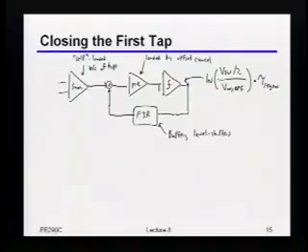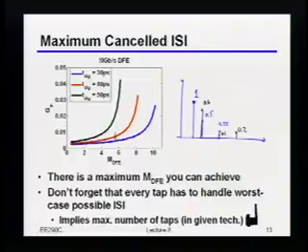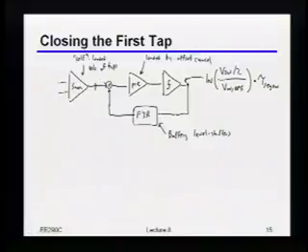Okay, and in particular, having to regenerate that small input signal can cost you quite a bit of time in terms of just regenerating, let's say, from 10 millivolts or 5 millivolts all the way up to something like a volt. Okay? So the issue you really run into here is that if you're running that DFE kind of close to the self-loading limit, but now you say, oh, no, oops, sorry, actually my comparator is a little bit slower, in this case, let's say, 10 picoseconds slower, all of a sudden, you might actually be completely infeasible, right? So especially if you have to deal with a lot of taps at that summing node, closing this whole loop can turn out to be quite challenging, okay?